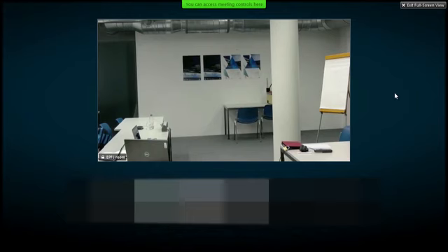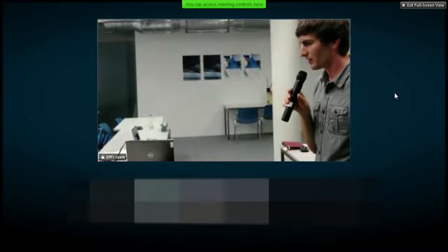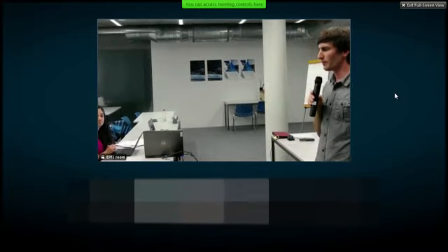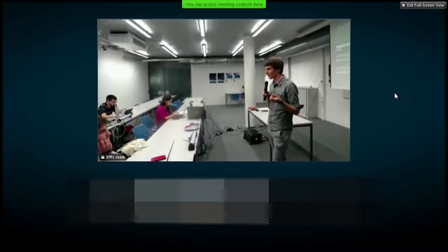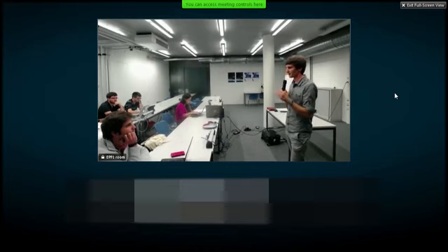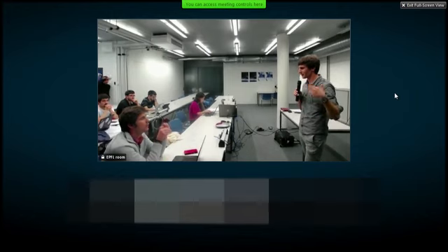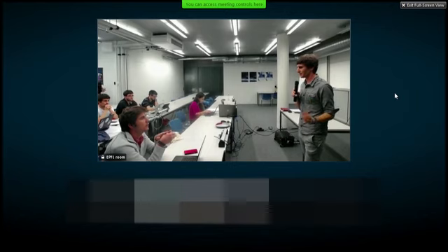Just maybe a technical question. Why did you choose to switch from your first communication to LoRa after? Yes, and why did you change? Before we had a kind of DIY component that was called HX1. There you basically had to modulate the signal that you're going to transmit yourself. And it was just way too complex. With the new component, you can just send commands by UART, and it will just do its job, and it has higher range as well, and lower power consumption.